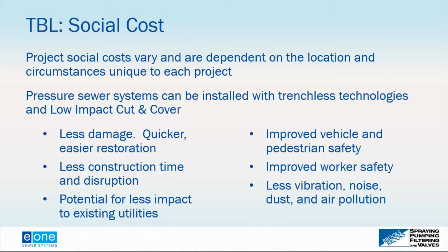With the pressure sewer system, you have the ability to flexibly alter your standards horizontally and vertically. The rules of separation between utilities would still have to be followed, but you don't have to dig a deeper excavation. You just got to make sure you got that separation between water and sewer covered. It provides for improved worker safety, improved vehicle and pedestrian safety, and less vibration, noise, dust, and air pollution.